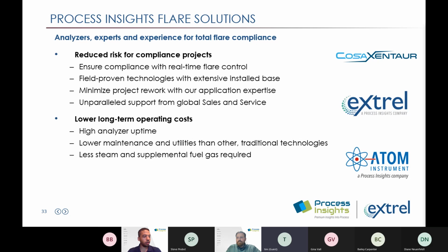Yep. What we've done in many cases is, in addition to the scan they would use for compliance, that quick 15-second scan that Chuck was mentioning, we can do a broader scan that's run periodically and look at many of those peaks of interest that might be used by scavengers or other sulfur compounds, heavier hydrocarbons, aromatic compounds. And then during flaring events, or even under normal conditions, engineers are interested in what's present. We can go back and look at that historical data.